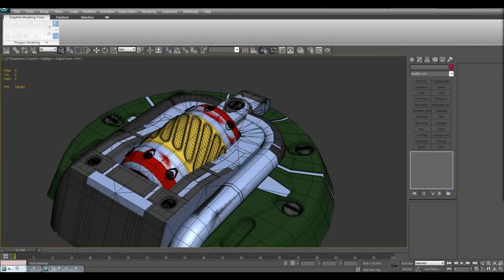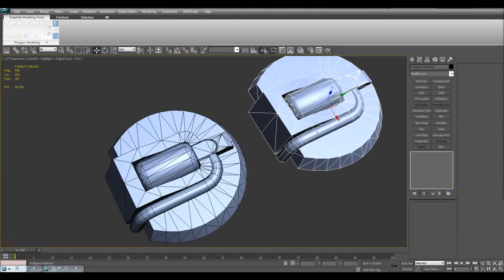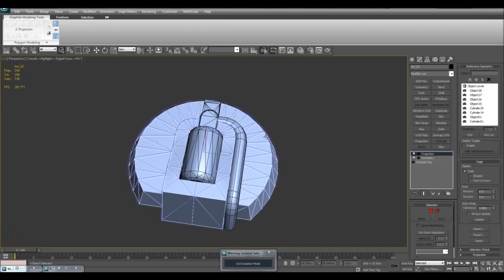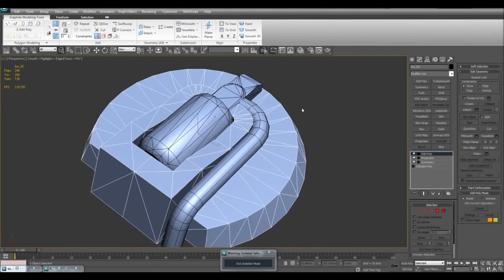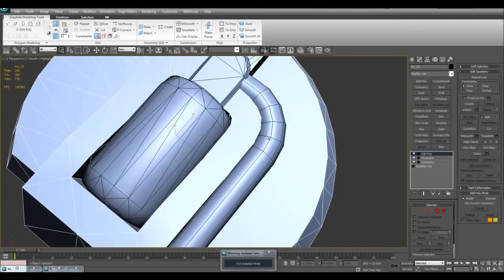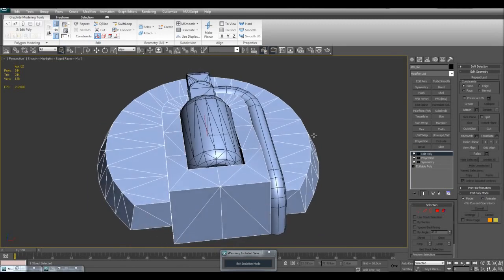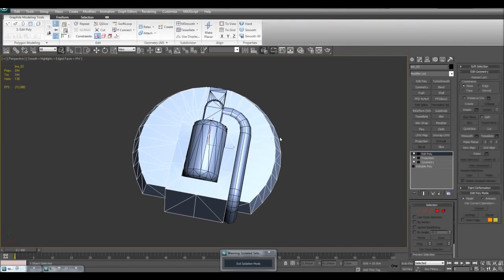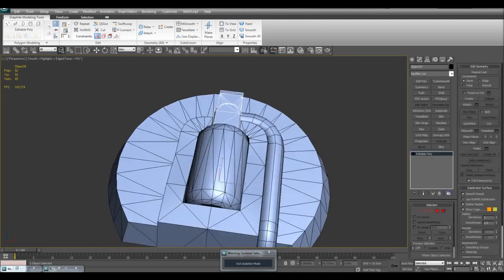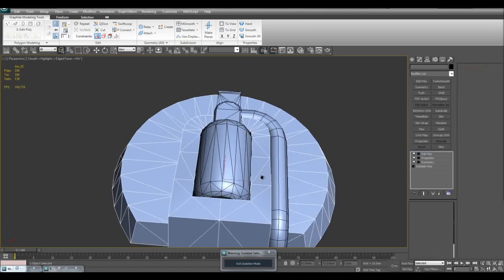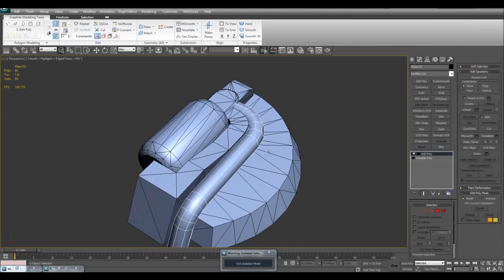But before I start with that, I just want to make sure that you've got the process down for how we can create a low polygon mesh. Just real quick, what you need to do is determine which parts of your geometry will be symmetrified and which parts will have mirrored UVs, mirrored textures. So decide that, and then I can go ahead. I decide that, for example, this piece of geometry and this one will be mirrored, whereas this one and this one will have unique textures on the left and the right side. So now that I've determined that, I'll go ahead and delete the left side. And for this pipe, the left side is already deleted.